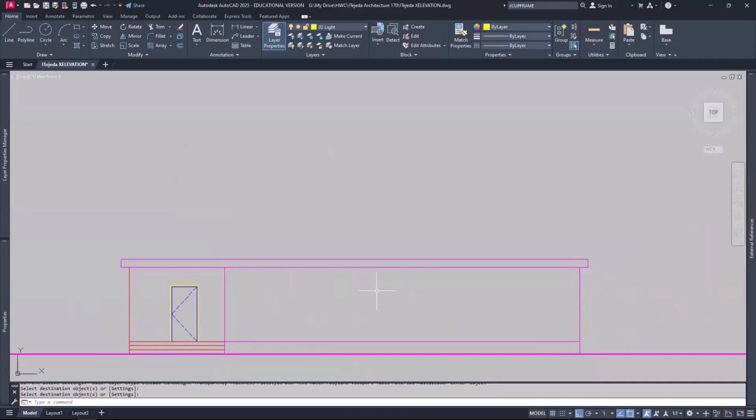So remember how I just kind of modeled it real quick and I told you that there was a thing called the rise and run? I'm going to leave that alone for now. And I believe my roof height, and I'm just throwing the numbers out because I cannot remember, I think I made that roof 6 feet high. So I'm going to type O, enter, and I'm going to type in 6 feet, enter. I'll take this roof up because I think that's what it was.